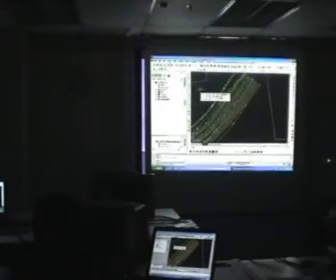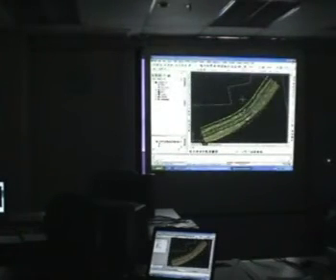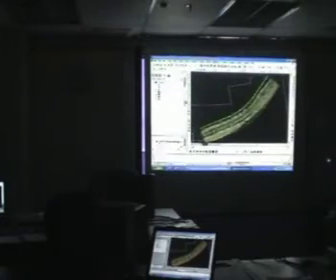Of course, Civil 3D does not come with that wonderful package of Autodesk Viz, but it comes with what is useful in Viz for civil engineers. So we call it Viz render. We've got a corridor here that we want to see what it looks like, maybe if you put the asphalt on top, maybe you've got the grass at the side, you want to see what it really looks like. That's what Viz render is for. So you just click link to Viz render.